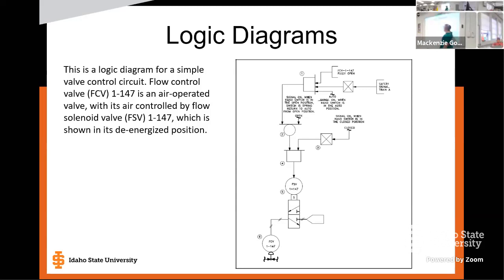So, good. And then here, for this logic, the signal is on when the hand switch is in the open position. So here, this is on, and we determined that this is off. So what's coming out here? On, because it's an OR. If either one of them is on, it's on. Signal is on when the switch is in the closed position. So here our signal's on. What happens here? No signal. So now there's an off and an on. So what's this? Off.